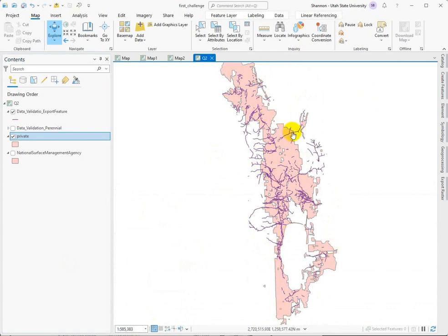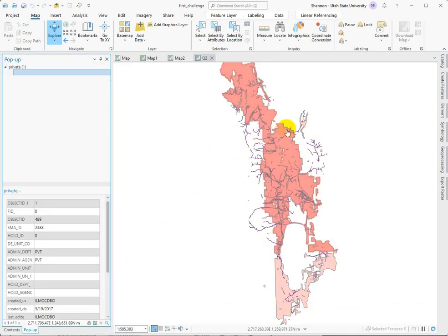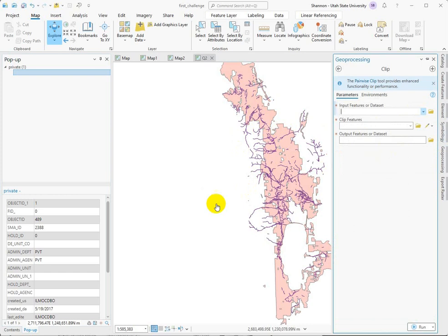And I would go ahead and clip this myself. Selecting by location is going to pick up lengths that crisscross over the boundary, and I don't want to have to deal with completely within or intersecting or anything like that. I'm just going to go ahead and cut it. But in this case, we don't care, so a clip works. But intersecting cuts it the same way, but appends both sets of attributes to the output data set.